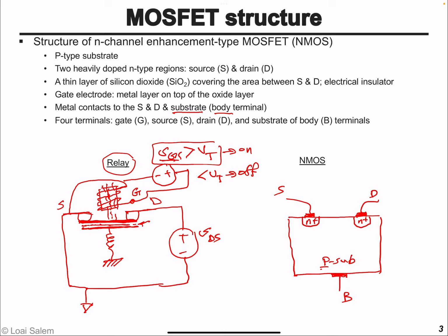Generally, when you have a p material that's touching an n-type material, essentially you form a diode, a p-n junction or diode, okay, for simplicity. Again, this is a very simple overview of how a MOSFET or a transistor operates as a switch. And so here we have two back-to-back diodes, because this terminal is the p substrate, and then we have the n region.